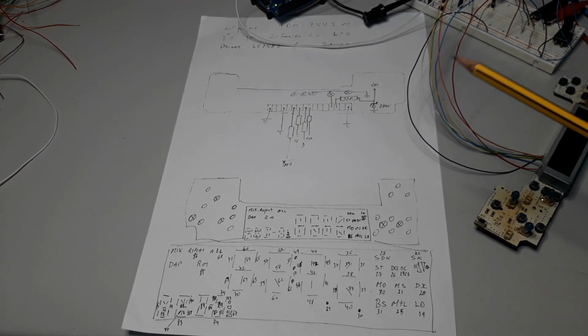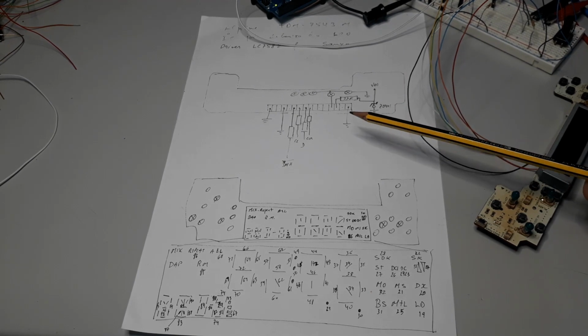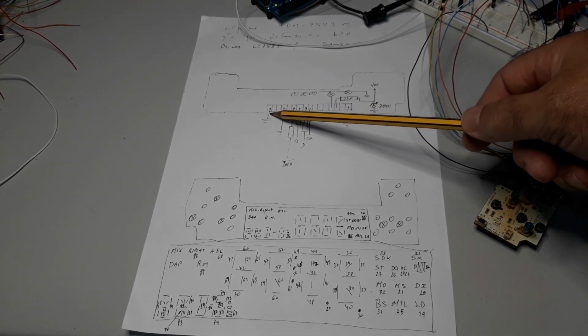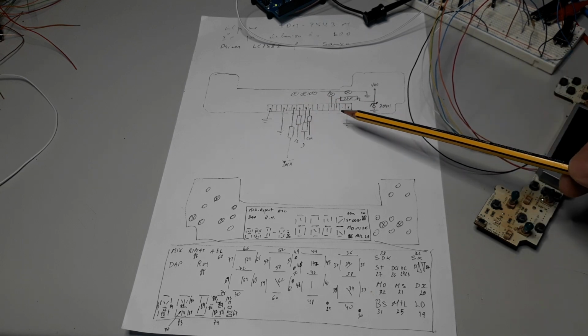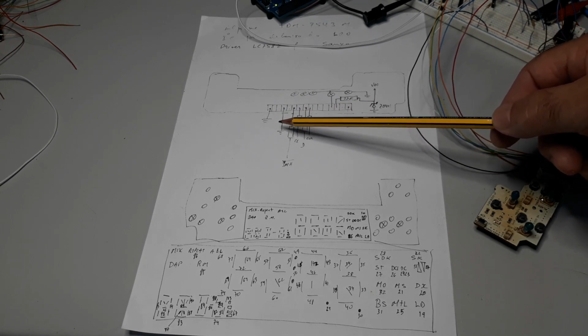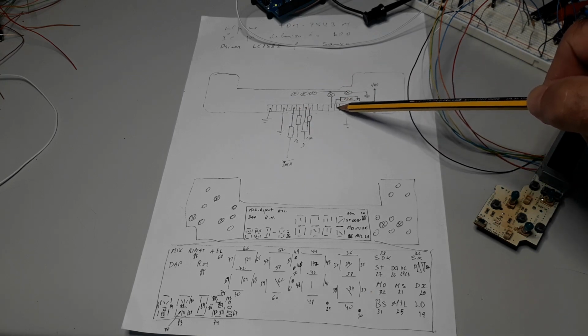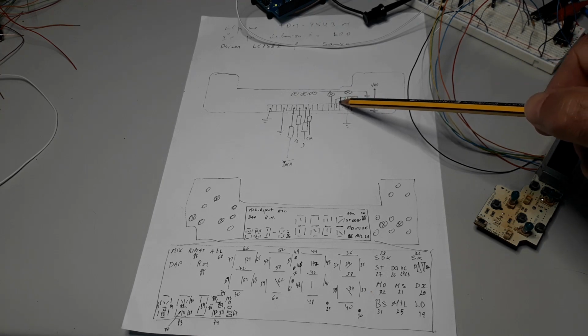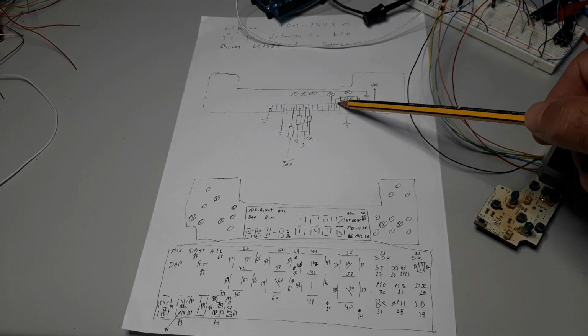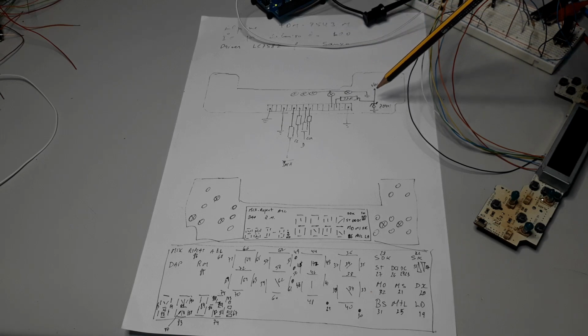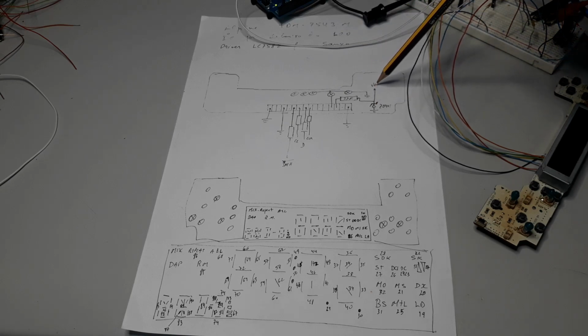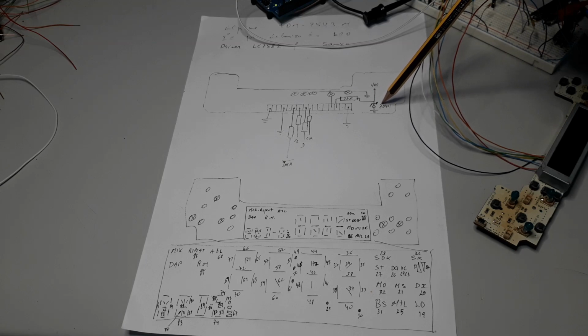The connections I have done to bring the panel to life again are GNDs at both sides of the connector. Here you have one more GND. At this point, pins 1, 2, 3 at right, you have one input for the power that will be used to provide the 5 volts to the IC. They use a resistor of 2.7K and a Zener of 5 volts DC.